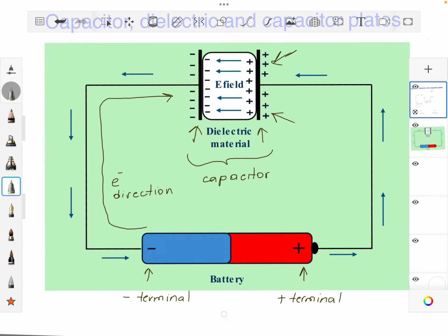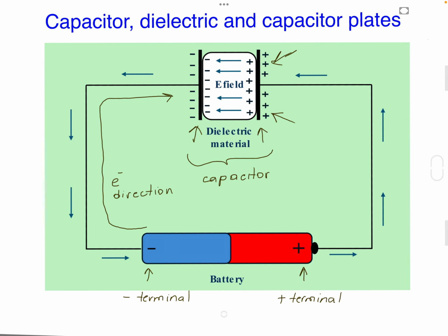Inside the dielectric, there is no electron movement. Please ignore for now the electric field that I wrote; I will explain it in a minute. Inside this capacitor, there is no electron movement. So I'm just going to write here: no electron move. That's the reason why we have a capacitor here. Otherwise, we wouldn't need all this; we would just draw a straight line there. It's an insulator, but the electric field across it forms instantly as soon as charge builds up on the plates.